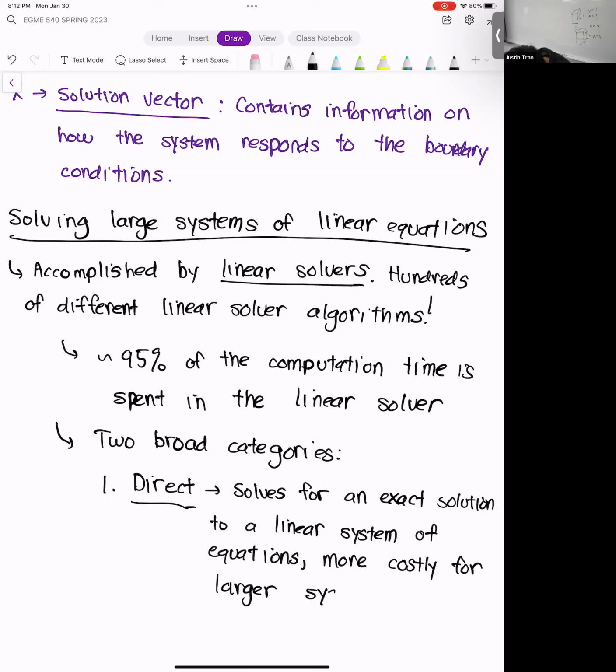For ANSYS Student and ANSYS Academic, which are the ones you're using, I think direct is the default setting. The reason is the element limitations they put in the student version. Direct is often the best course of action. The simulations never get too expensive, and so solving directly is often good.